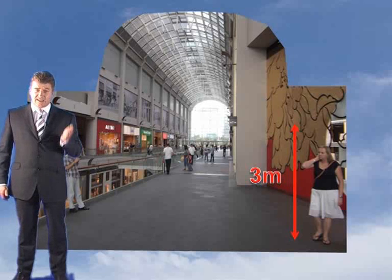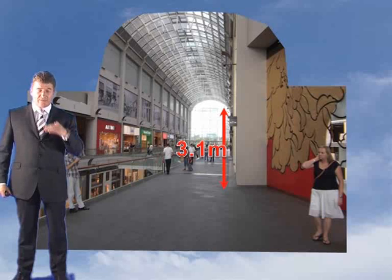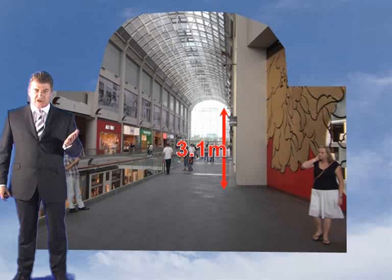However, in this case, it's also desirable that smoke should not be allowed to enter any shop unit. And the highest shop unit is 3.1 metres. So with a clearance of 0.5 metres, which is what you'd normally achieve, we need to increase the clear layer height to 3.6 metres. So that is the design objective, a 3.6 metre clear layer height.